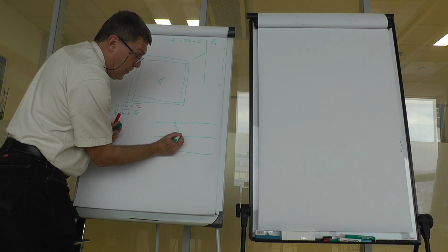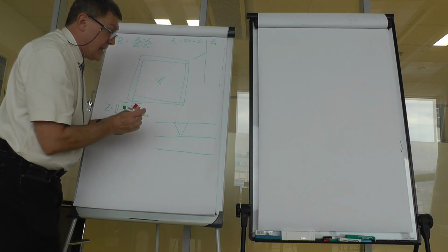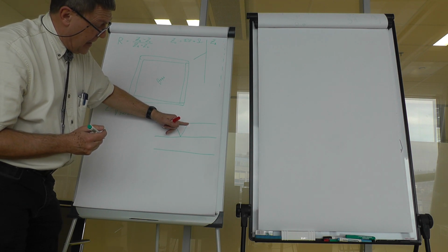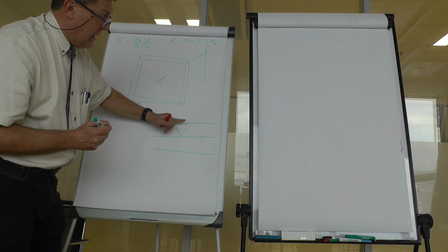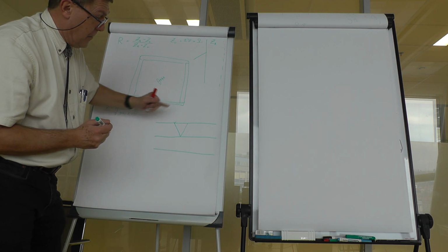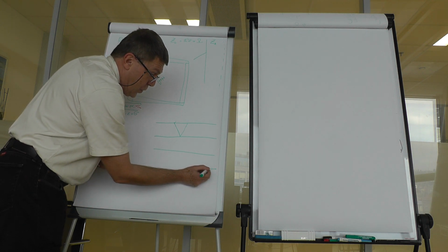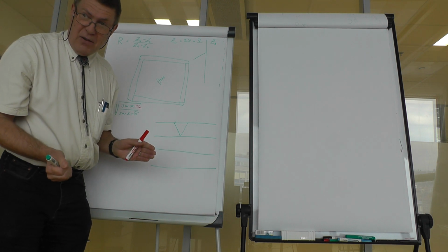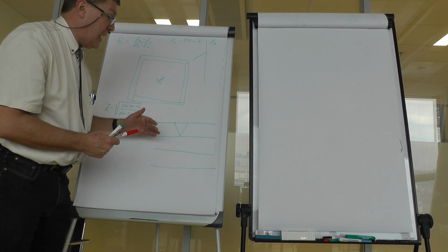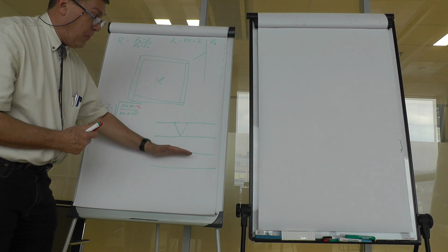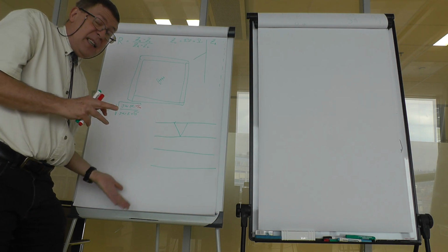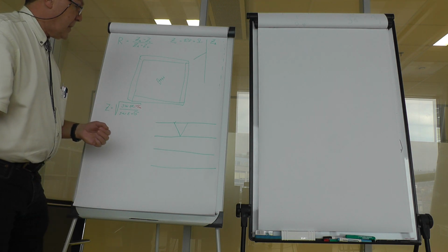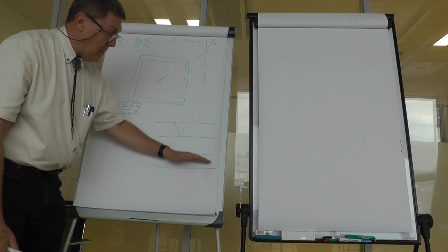But this wave reflected back gets a little bit damped on this way and a little bit damped on this way. So finally, you would get sufficient attenuation, and this story repeats so that, say, 5 to 10 layers of material which with increasing damping factor and increasing reflection at non-intended angles is contained in the matching structure.